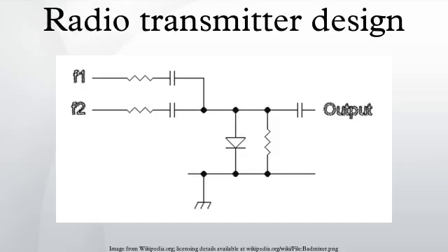A directional wattmeter indicates forward power, reflected power, and often SWR as well. Each transmitter will specify a maximum allowable mismatch based on efficiency, distortion, and possible damage to the transmitter. Many transmitters have automatic circuits to reduce power or shut down if this value is exceeded.